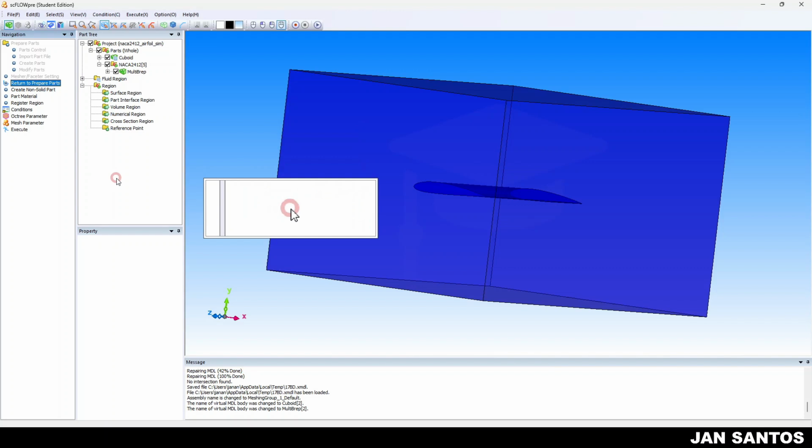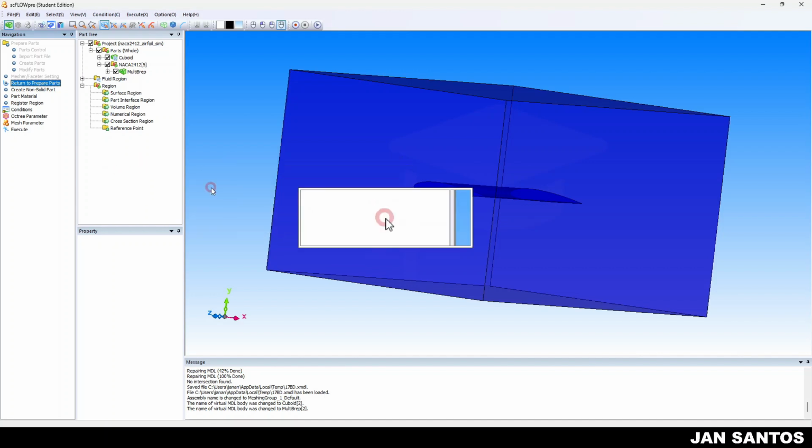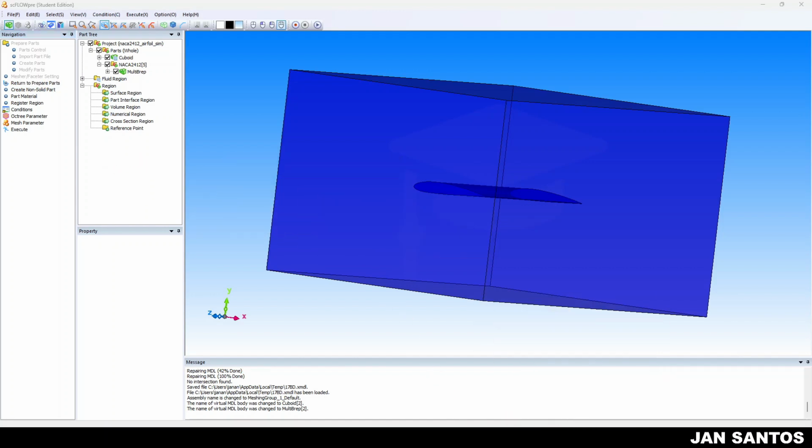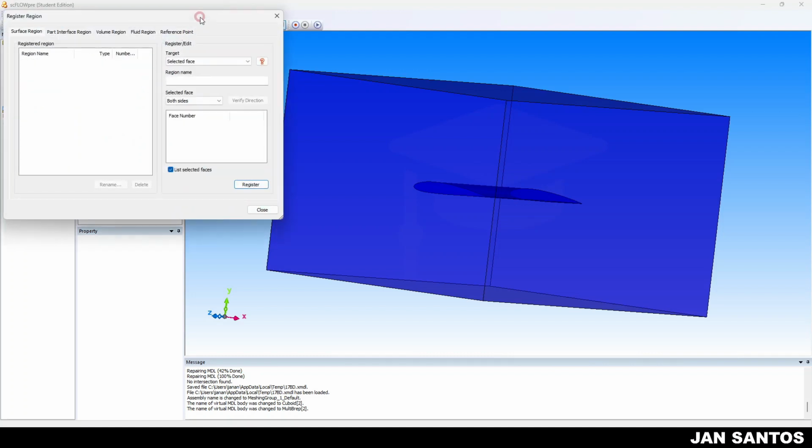Okay. Once you're satisfied and moved on, we can go ahead and build our analysis model. So to begin, we're going to click on surface region. I no longer need to zoom in since it will be highlighted blue. It is under our part 3 region, surface region.